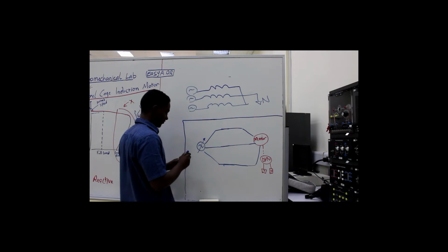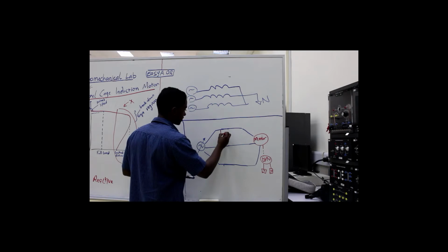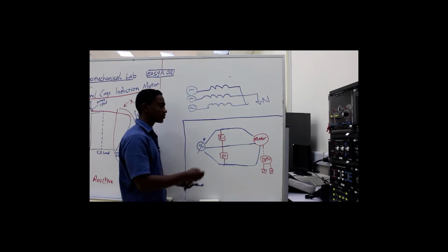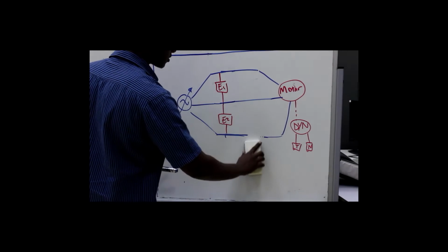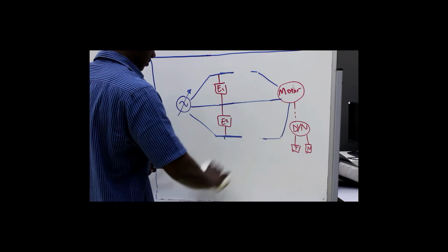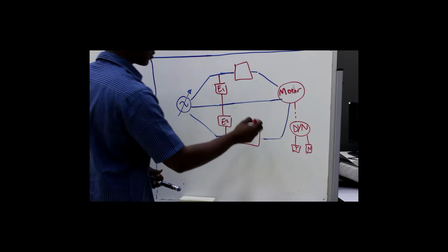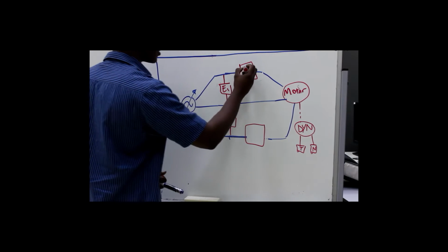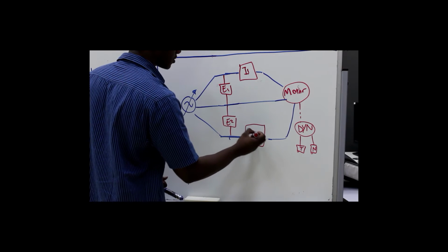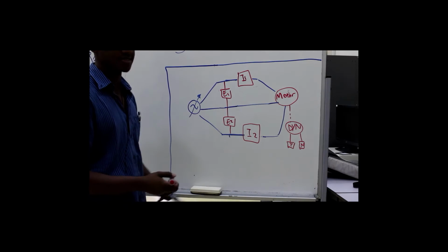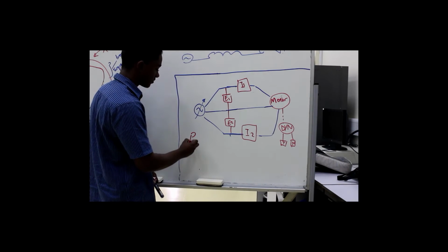So we're going to connect a voltmeter between these two lines. Let's call it E1, and another here, let's call it E2. So we have two measurements of the line voltage, and we want to measure the line current as well. So we'll take two measurements also. So we're going to put a current meter in series. Have I1 here and I2. E1 and I1 and E2 and I2 together work as a wattmeter to give me the line power.